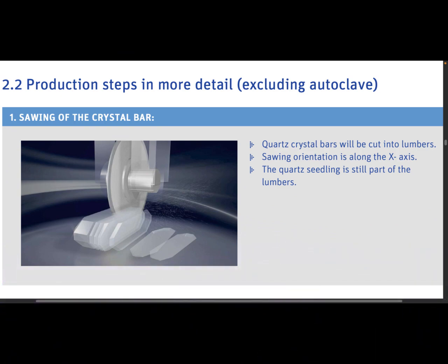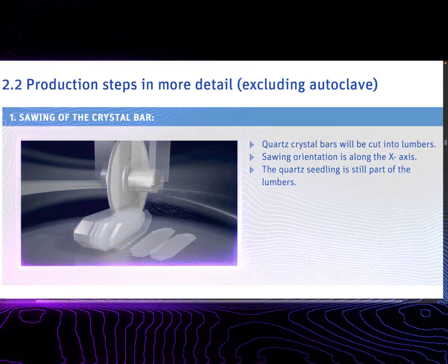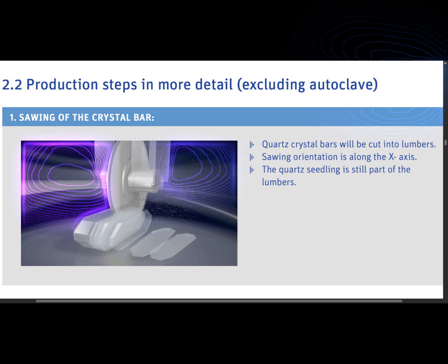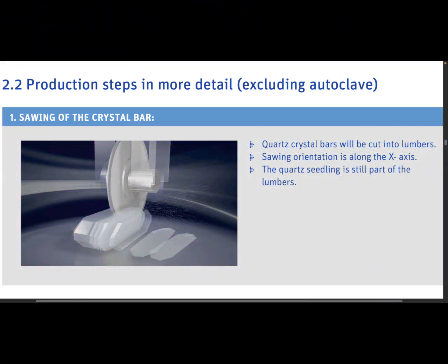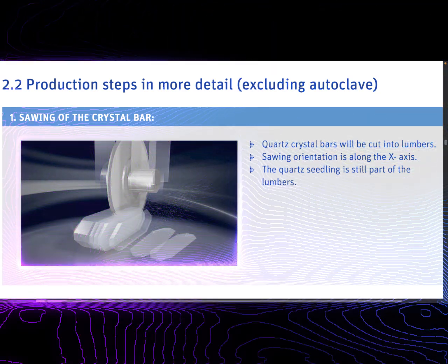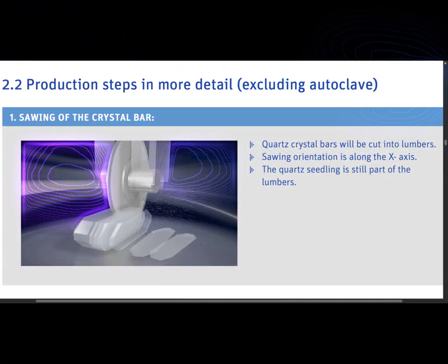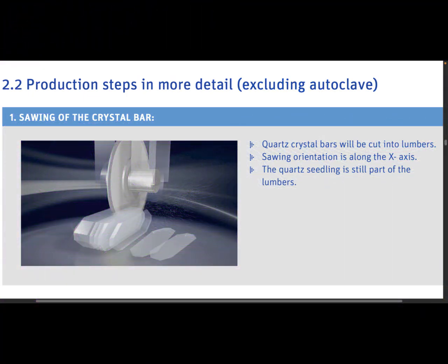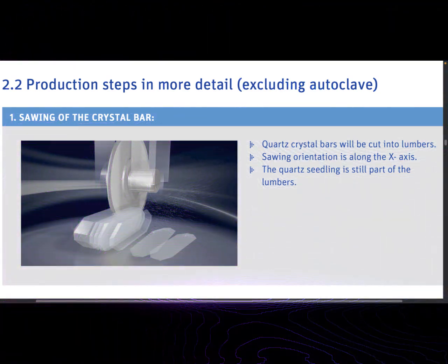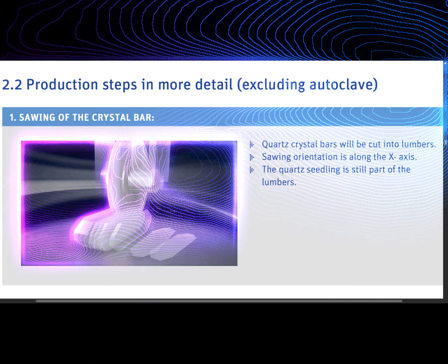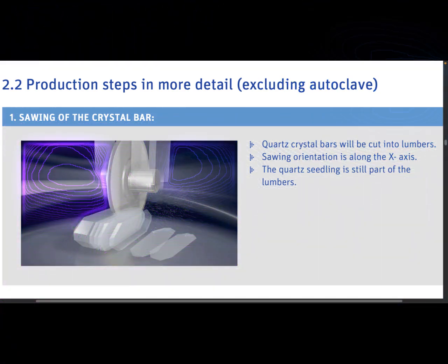Oscillator circuits. A crystal oscillator requires a high-gain inverting amplifier. This can use a transistor or an inverting logic gate. Crystal oscillators. You can also buy ready-made oscillator modules that contain a crystal and the oscillator circuit. You just need to provide a power supply. This is often the simplest or most cost-effective solution where the device does not have an integrated oscillator circuit.